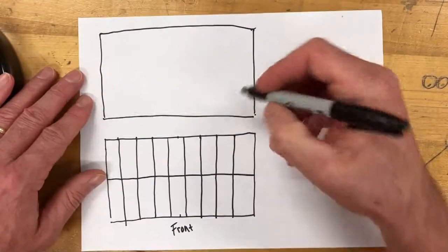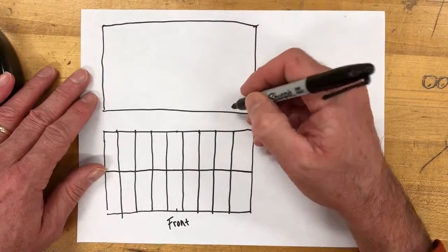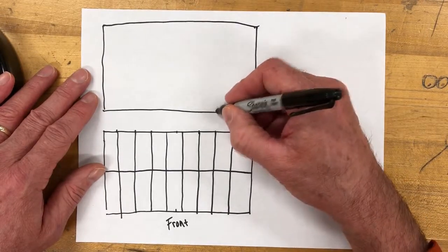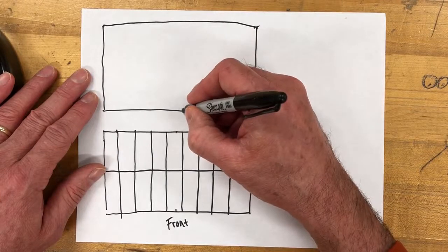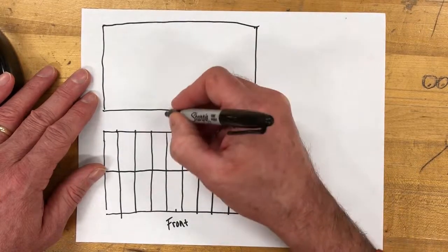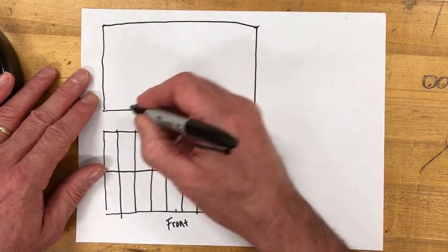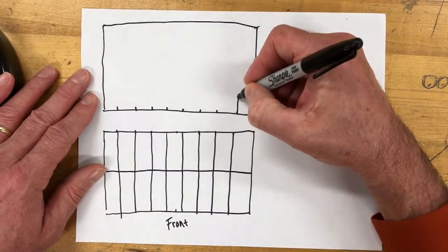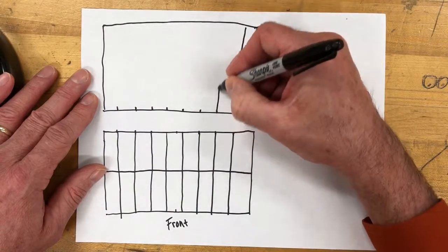So anyway, the roof trusses, which would be the thing that I would be viewing up here in the top view, are basically in the same position as the wall studs. So I'm just projecting up some lines here, some dots there indicating where the studs need to go, and the trusses on top of them, okay? So now I'm just going to draw some lines across here like this. And see, it's a rough sketch.